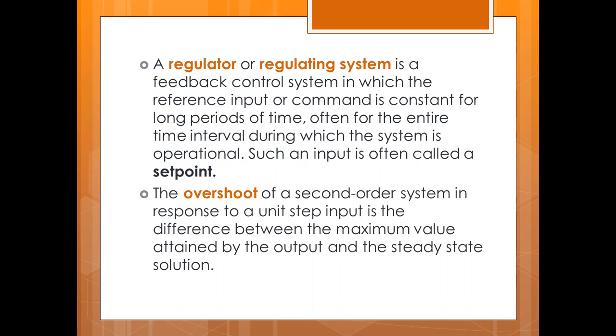So we have discussed these terms actually, servo and regulator problems, but they are defined differently. So a regulator or a regulating system is also a feedback control system, in which the reference input or command is constant for long periods of time, often for the entire time interval during which the system is operational. So the thing that you need to understand here is that the reference input or command is constant for long periods of time. Such an input is often called the set point.